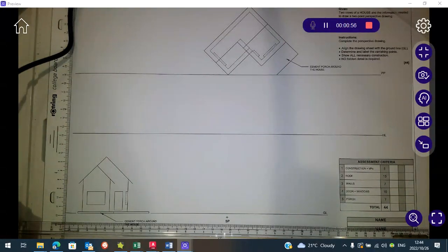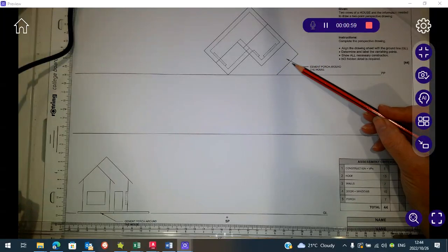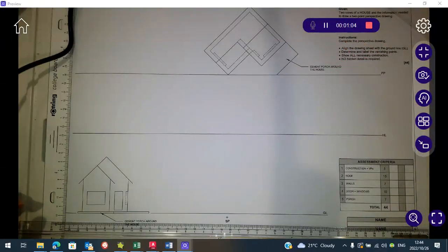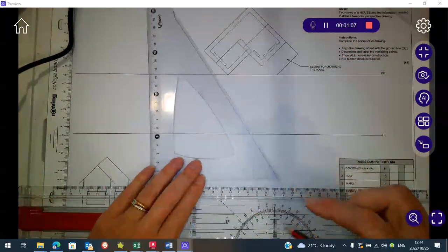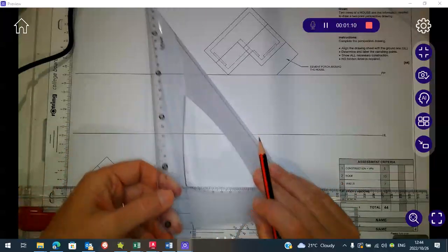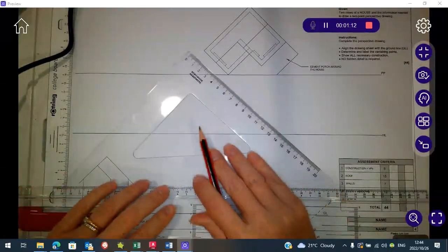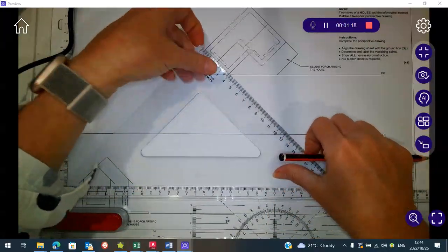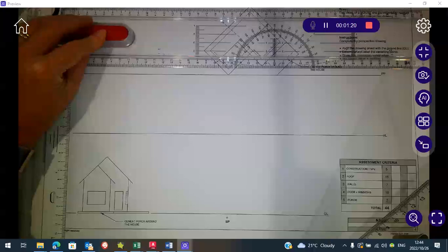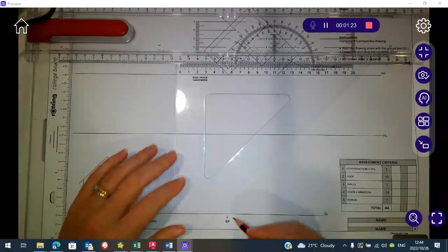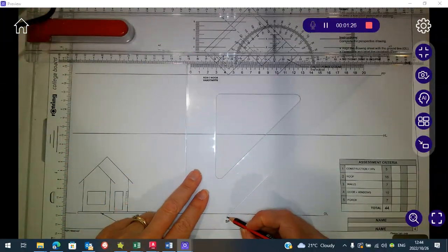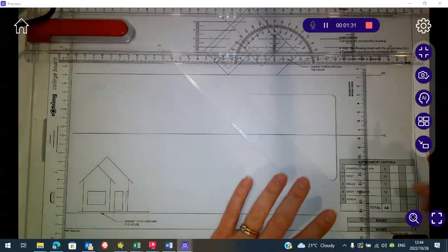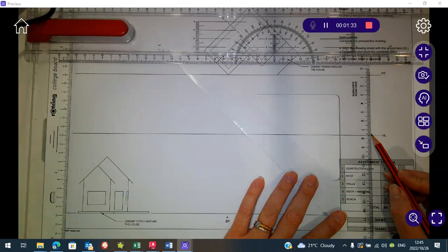do these drawings. First thing you are going to look for is the angle that our object is inclined at. So it's either going to be 30-60, so straight away I can tell you now that it's not 30-60. So I'm going to take my 45 and have a look, and you'll notice that it's at 45. So in order to find your vanishing points, we are going to draw a 45-degree line from the standing point or the stationary point. We project it up till it hits the picture plane, and then we project it down to where it crosses the horizon line.